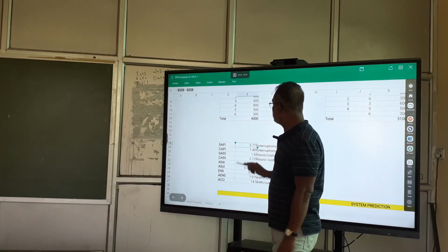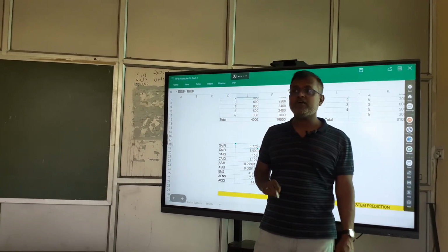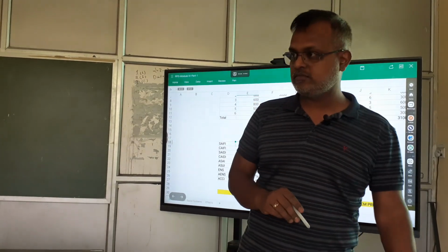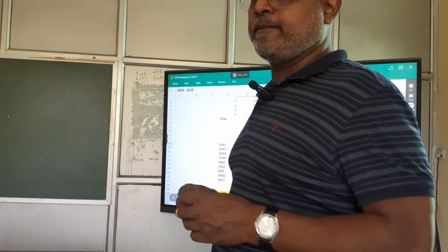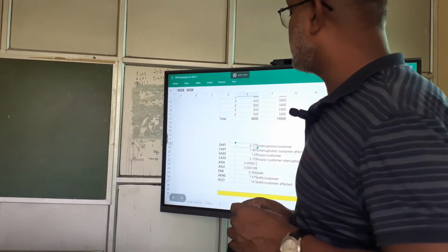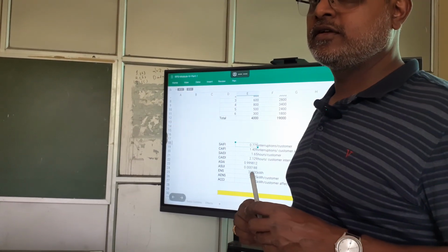Now what's the numerator? Numerator is equal to the number of customer interruptions. What is the number of customer interruptions? 3100.